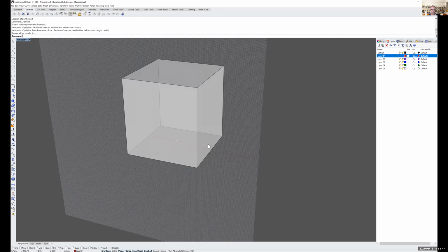But you found the midpoint of your curve, right? Yes. That's what I'm trying to figure out. How did you do that? Just the snaps down at the bottom. Can you see my mouse down here? Do you have mid selected? Yeah. Okay, so if you mouse over, you should be able to find the mid as you move along the line. It'll say end, an intersection, and it'll say mid for the midpoint. Okay, that's okay.